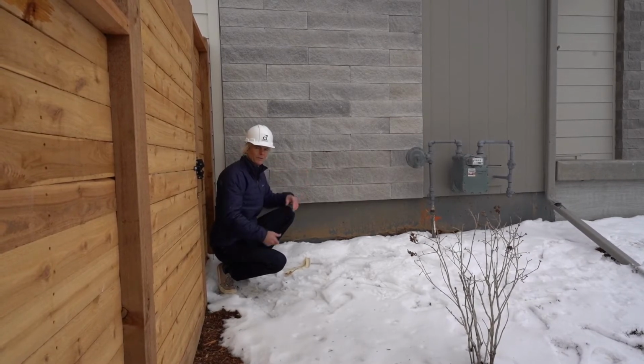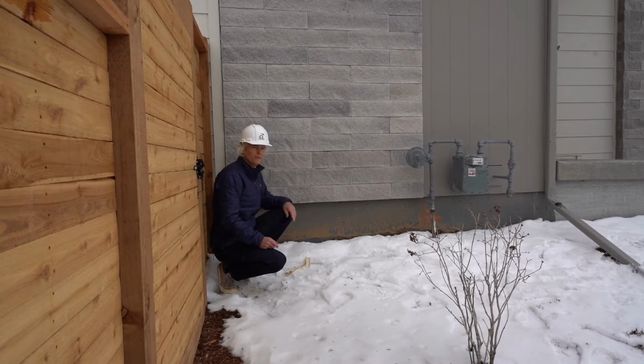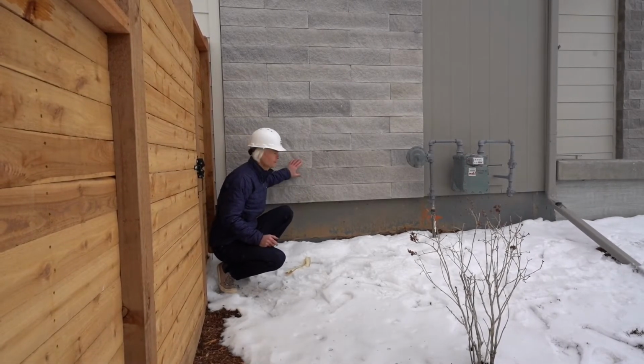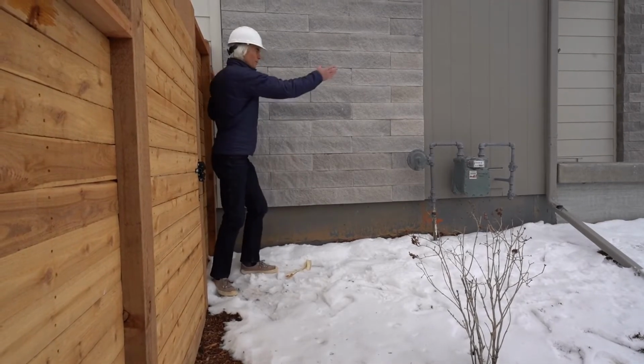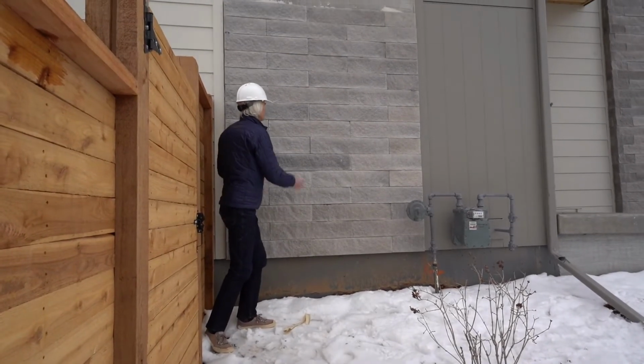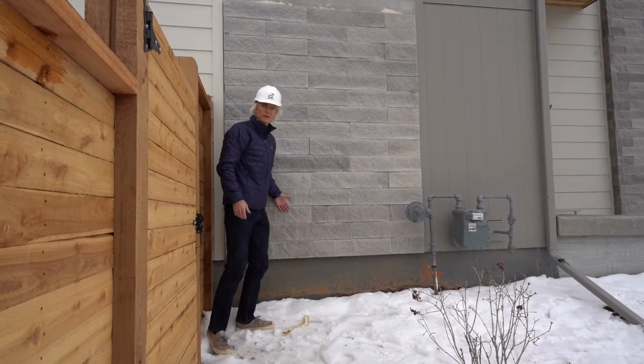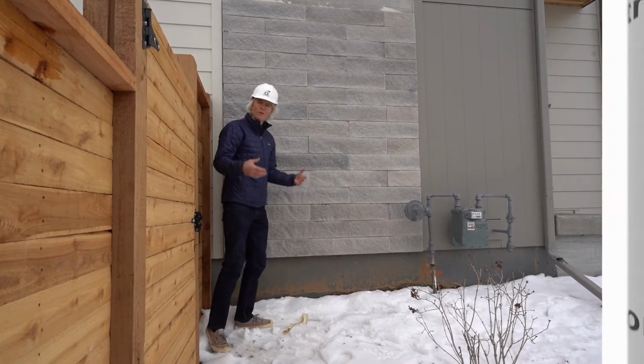This is on the windward side of a building. This side of the building is going to be hit with water every time it rains in this particular climate. So something to really think about is how we detail these different claddings, and even how we provide drainage or ventilation through this long, tall, slender wall right out the bottom.